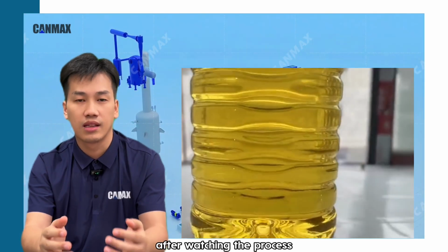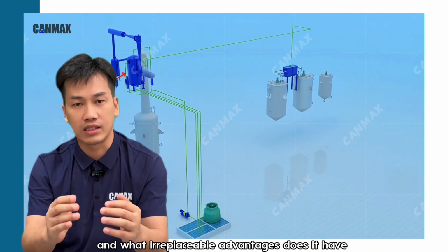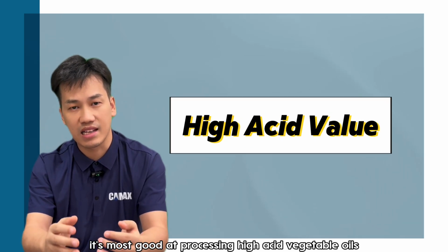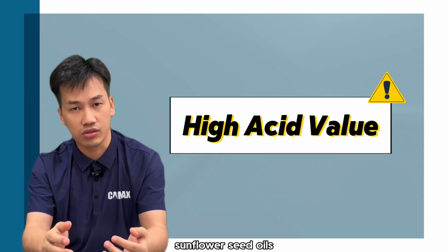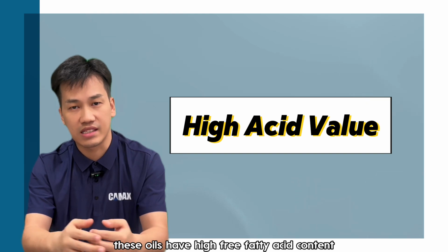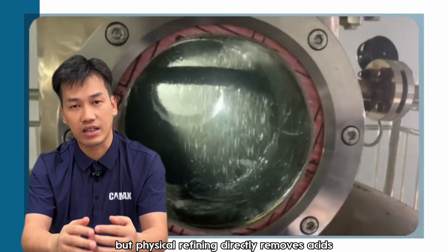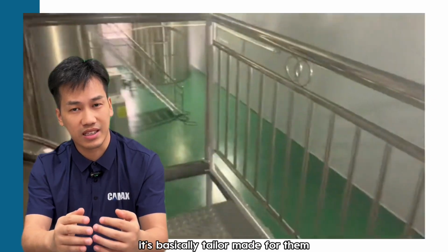After watching the process, let's highlight the key points. Which raw materials is physical refining suitable for, and what irreplaceable advantages does it have? First, suitable raw materials. It's best at processing high-acid vegetable oils, such as palm oil, rice bran oil, sunflower seed oil, and some low-quality crude olive oils. These oils have high free fatty acid content. Using chemical refining would produce a lot of soap stock, leading to high loss and waste. But physical refining directly removes acids through distillation, and the loss is more controllable. It's basically tailor-made for them.